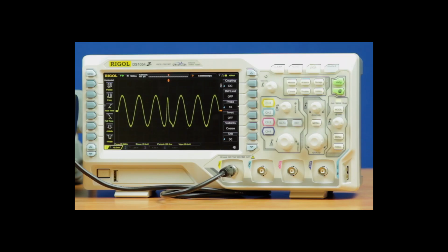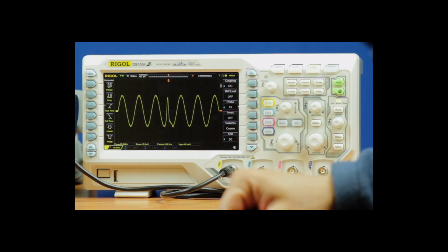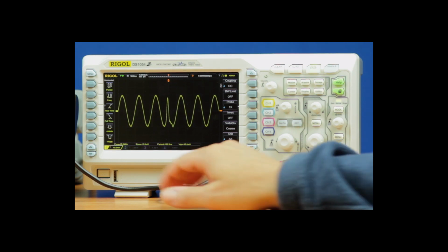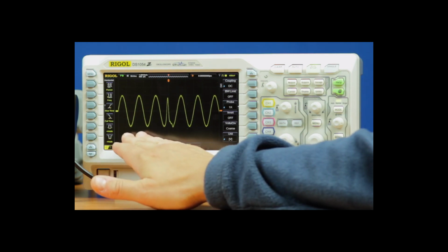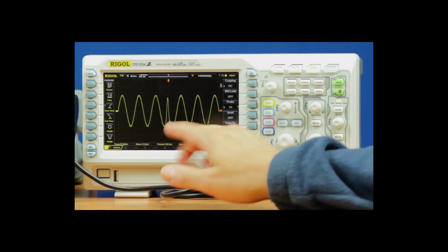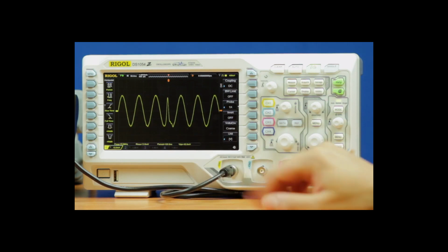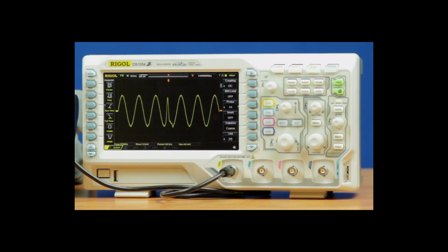And here on the scope, we can see we're now triggering on the change in that phase using a pulse trigger mode. And now you can see that on the left side of the screen, the sine phase is normal. But then, right as it switches in the center, you can see it's offset by 1 division of where it otherwise would be. So it's inverted or 180 degrees out of phase. So that is a single transition going back and forth of 180 degrees in phase.